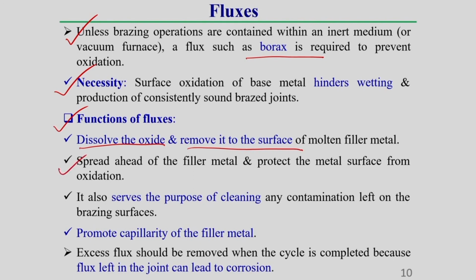It also spreads ahead of the filler metal and protects the metal surface from oxidation. So, this flux is spread ahead of the filler material, and during this movement of the flux ahead of the filler material, it cleans that surface beforehand. After that, the filler material passes through that region. That is why it also protects the metal surface from oxidation.